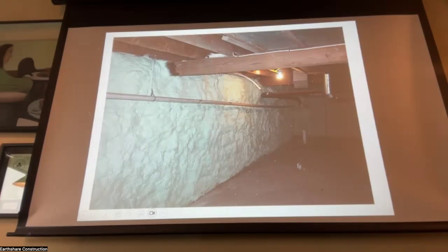So if the basement is normally 60, and from a foot below grade down to the bottom is just a sheet of membrane, it keeps the moisture out. You don't have evaporation of water coming through the stone wall into the living space. And then the water running down behind the membrane can go into a gutter.